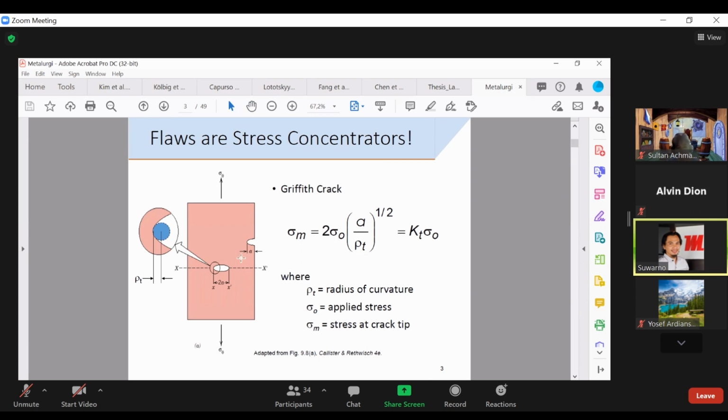So you find a crack, as you remember from Metal 1, and calculate how much it grows. If you remember from fatigue, if you have an initial crack, then the crack can grow, and you can calculate how long it goes until it reaches a critical crack length.